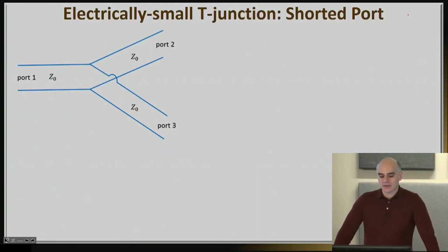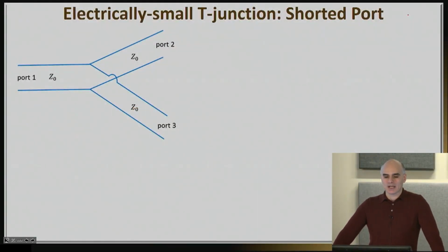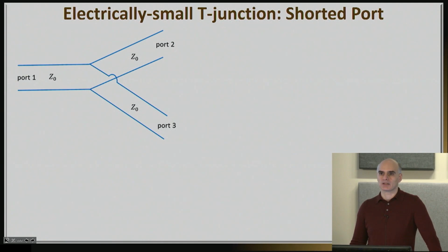Now, in this part, I would like to show you the power of knowing the S parameters for a network if the conditions do change. As you may remember from the previous video, the main idea here is that in order for me to calculate the S parameters, I must terminate the network to its own characteristic impedance for each port. For example, when I did the calculation for S21, I had to make sure that A2 and A3 are equal to 0, which means that each of the ports 2 and 3 have to be terminated by their own characteristic impedances. That is necessary to calculate the S parameters.